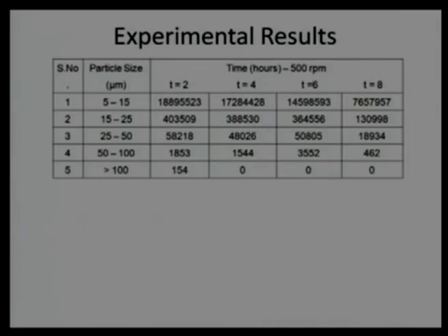We can say the starting case may be severe wear, but it is still controllable. It is moving toward the mild wear side. Interestingly, we found a couple of particles having size more than 100 micron, and when we studied mild wear and severe wear, we said that particles of about 20 micron indicate severe wear. So, most of the domain in this case will be severe wear, but it is not uncontrollable, it is controlled, and moving in the right direction. That means we do not have to worry too much, and we know this is the running-in time, or bedding-in time, where particles will be larger initially.